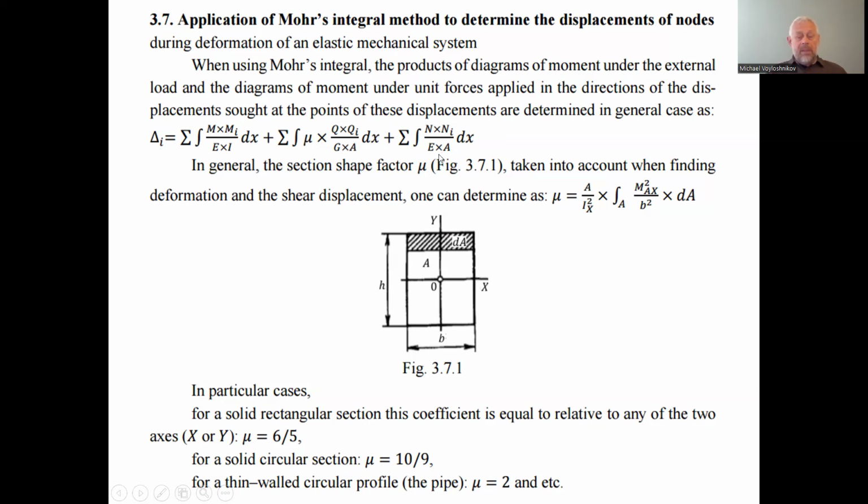And the last one is actual for the trusses, as we consider a truss as a connection of beams connected by hinges. These hinges do not transmit bending moments exactly, and we remember that bending moments are in a derivative interdependence with the shearing forces.